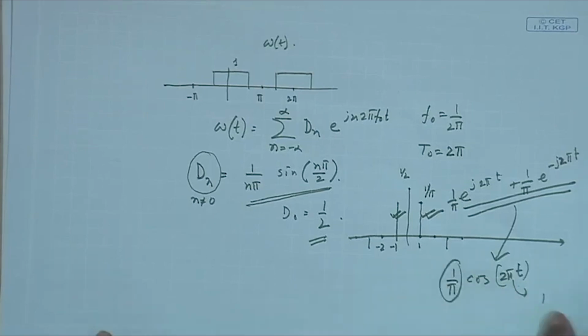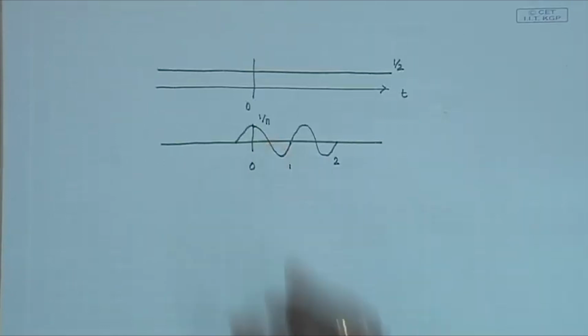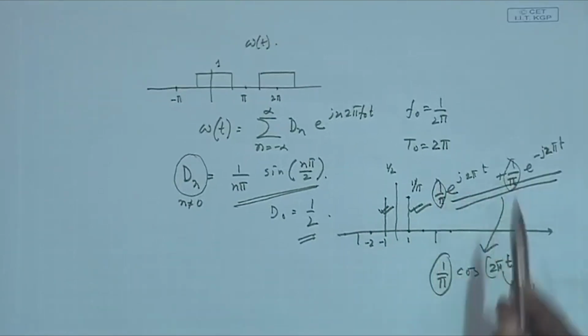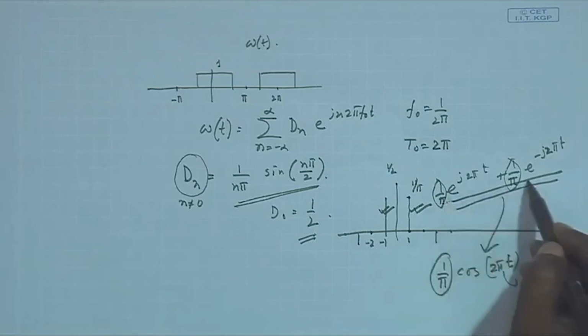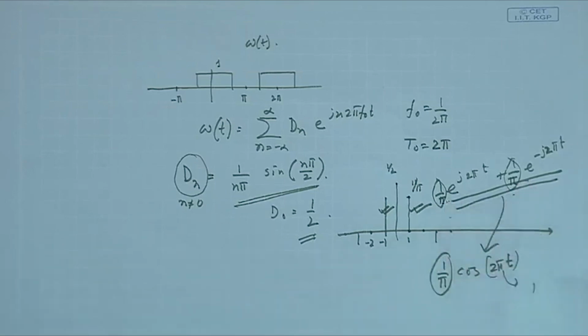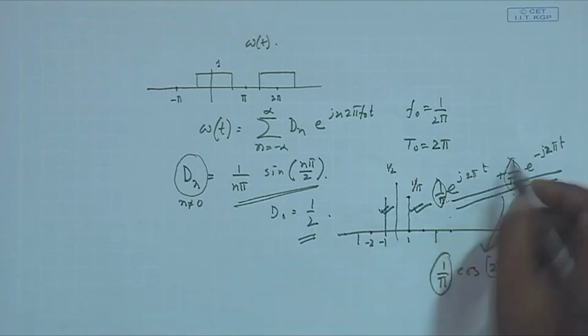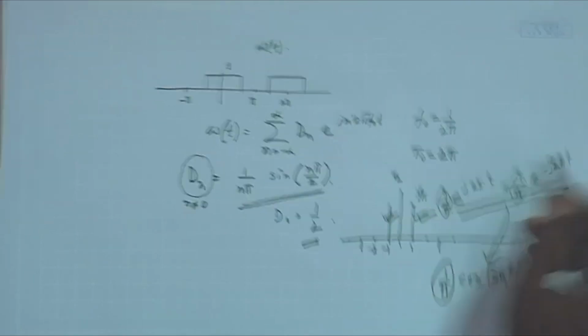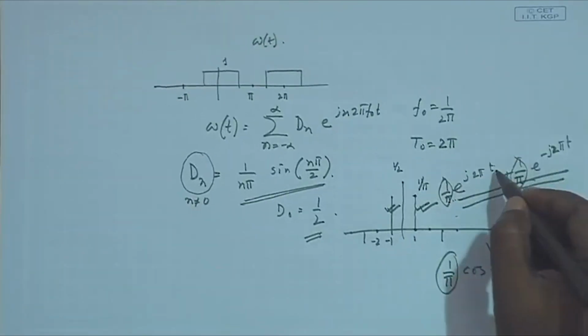So, basically whenever I am plotting this cosinusoidal, you need to understand that we are taking a positive frequency and the corresponding negative frequency, taking both the amplitude as well as the phase information. So, if you see over here carefully, we were actually taking the amplitude information and putting it over here, because the amplitude spectrum is even symmetric. So, we will have the same value over here. So, modulus of dn will be put over here and the phase of dn will be put over here, okay, plus and minus. So, that is the phase part, because here the phase is 0.